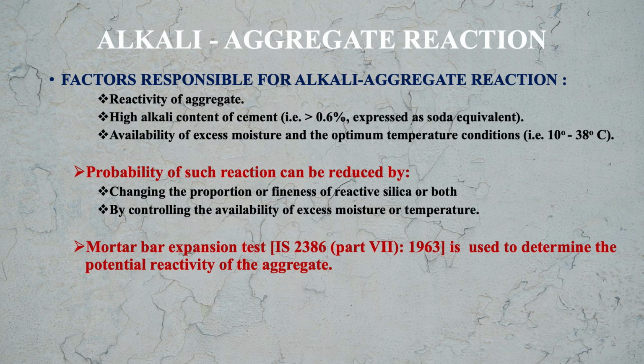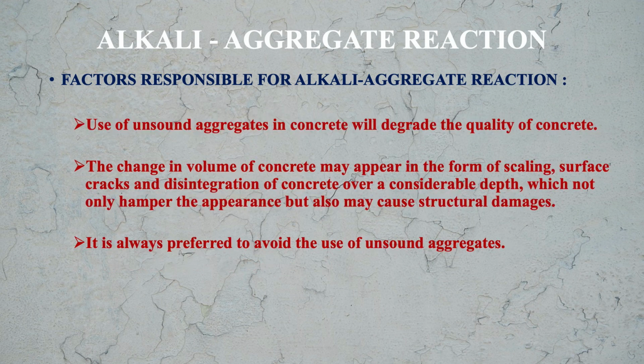The mortar bar expansion test as defined in IS 2386 part 7 of 1963 is used to determine the potential reactivity of the aggregate. The use of unsound aggregates in concrete will degrade the quality of concrete. The change in volume of concrete may appear in the form of scaling, surface cracks, and disintegration of concrete over a considerable depth, which not only hampers the appearance but also may cause structural damage. It is always preferred to avoid the use of unsound aggregates.